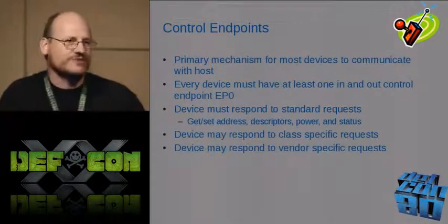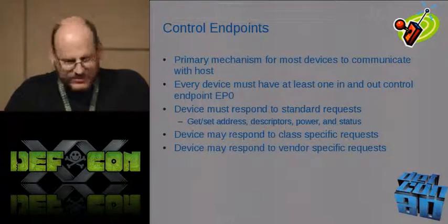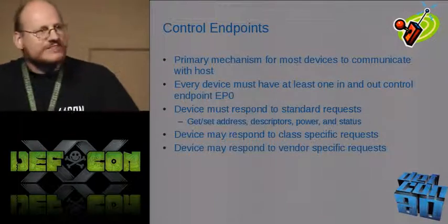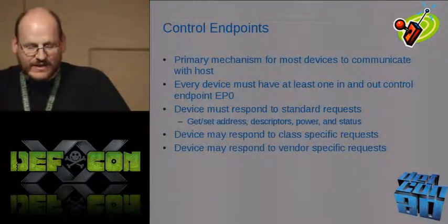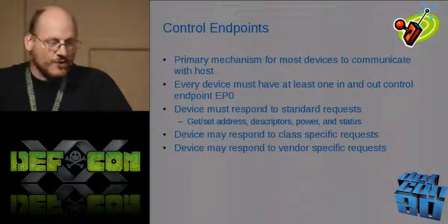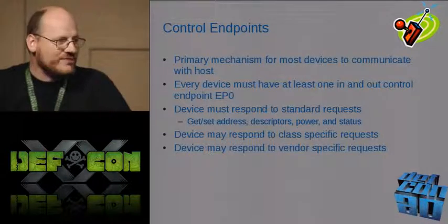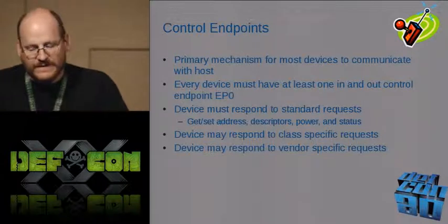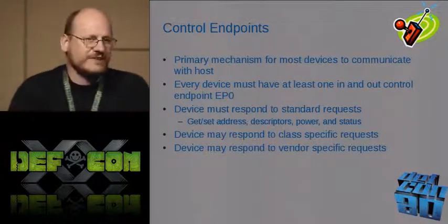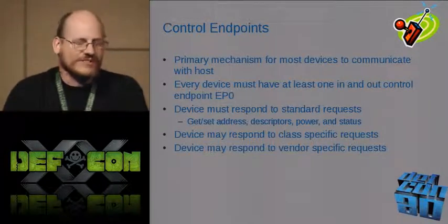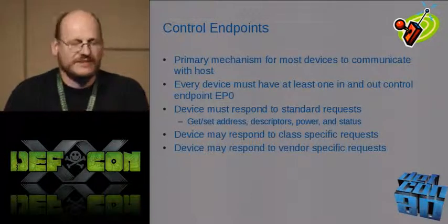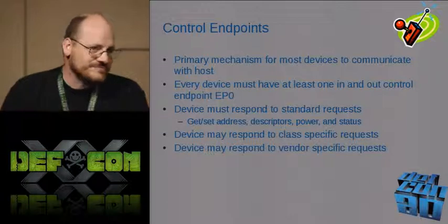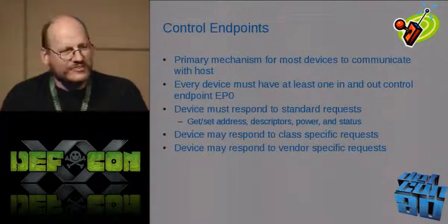All right, so control endpoints. Most devices use this to communicate with the host, and every device has to have at least one. We call it endpoint 0, not endpoint 1, because we don't program in BASIC. And the devices must respond to standard requests. These standard requests are things like, hey, set your address, give me descriptors, change your power settings, and what's your status anyway?